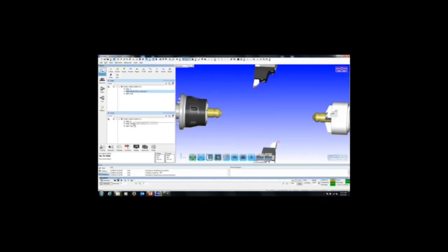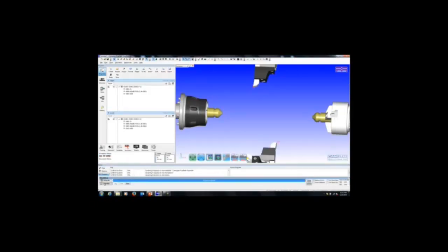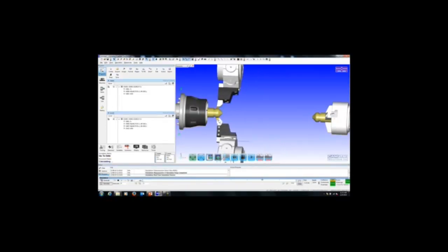Well, that worked so well, I'm going to go ahead and drag the one at the top down. I'm going to copy it, and I think I'll do some pinch turning. Tool position number 1's used, so I'll grab tool position number 3. Camplete updates the G-code automatically for the correct tool. And I'll go ahead and play this after I simulate it. Generate it, that is. And here we go. Bang, I'm pinch turning.